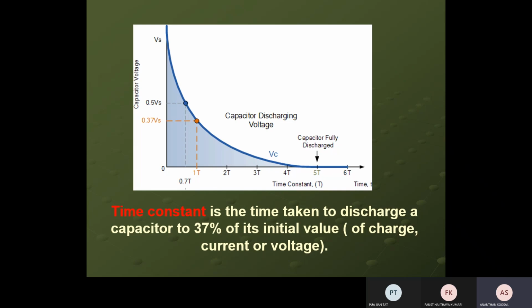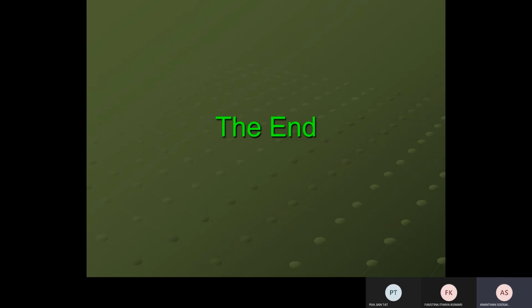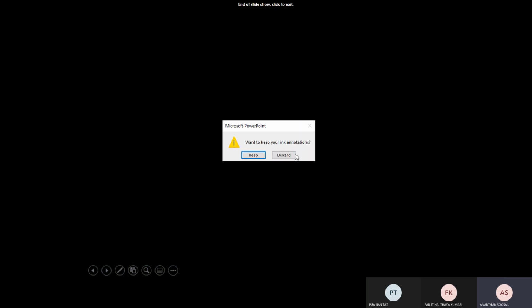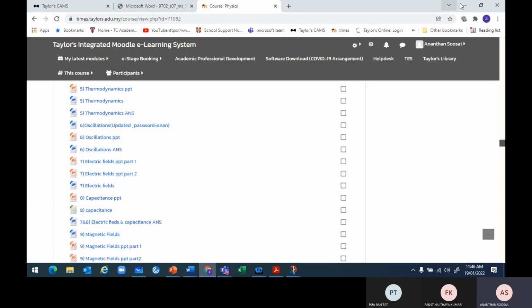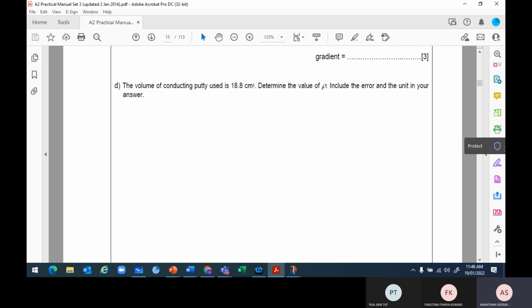So how do you make the capacitor discharge for longer? It depends on R and C. Use a big resistance and a big capacitance, and it discharges slowly. Big resistance and big capacitance means the discharging process takes longer. That's the conclusion. Okay, so we stop here. For the definition of tau, we say it decreases to 1